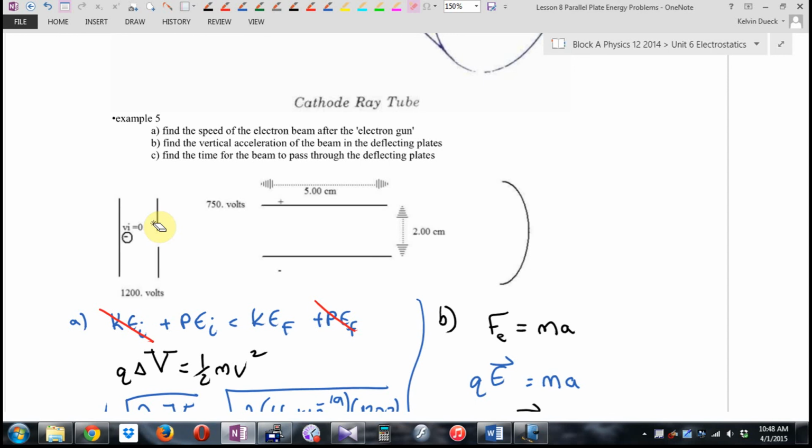If you're ever taking apart a TV, because you're a nerd, let it sit unplugged for about 3 months, because they use a capacitor that stores charge enough to kill you, and it will still be stored when unplugged. It will slowly bleed away, so leave it unplugged for 3 or 4 months before you start mucking around with it.